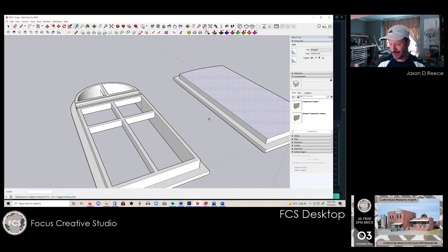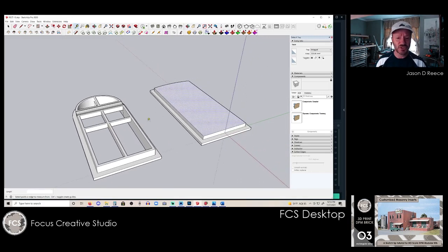Is it overscale? Sure, because in HO scale, 0.3 millimeters is basically an inch. So these would be 4 inches deep for what would be considered an old steel frame. And old steel frames are usually about an inch, inch and a quarter by 2 to 2.5 inches, which is pretty thin. So the width is actually pretty close. I mean, at 0.5 millimeters, that puts you at 2 1/4. No, I'm sorry, 1 3/4 inches wide. So that's acceptable to me. The original DPM windows, the mullions are 1 millimeter wide. So we're half the thickness on the windows, and we can get good quality prints.